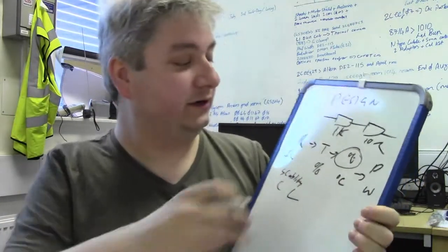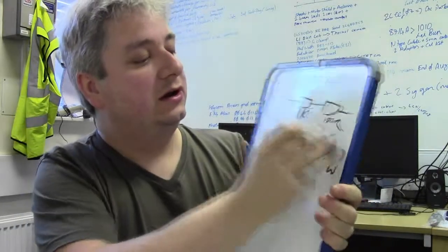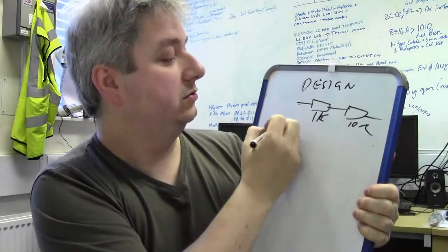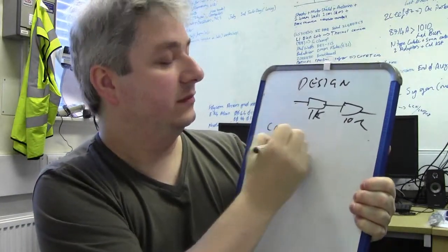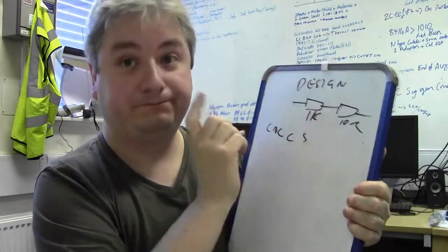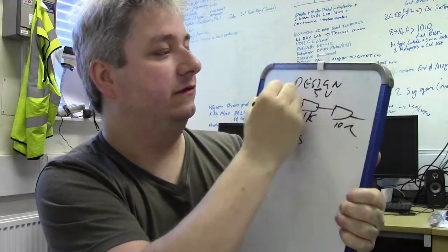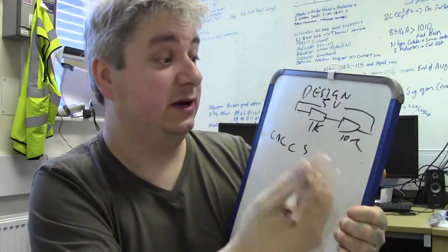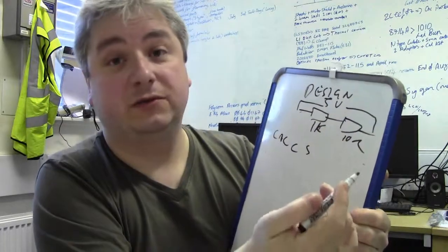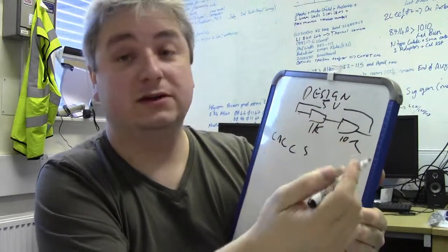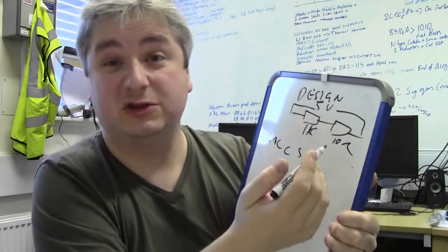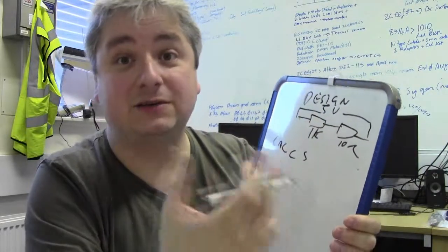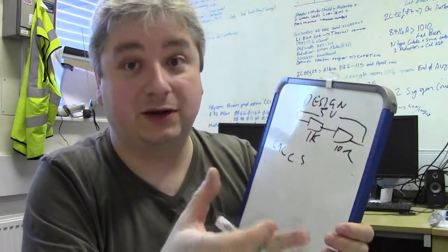That's all the sort of stuff that you have to pay attention to. These properties all boil down partly to your design calculations. If you've got your 5 volts going in, how much current flows through, you can work out the power dissipation. You can say, well, I'm dividing my voltage down, and if it's a 1% resistor tolerance, this is how much the ratio is going to vary slightly. Or if it's 5%, it's up to you how close you want your results.